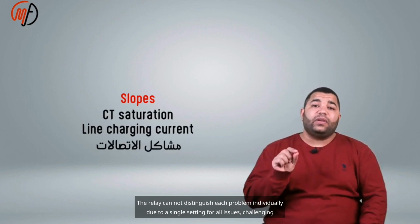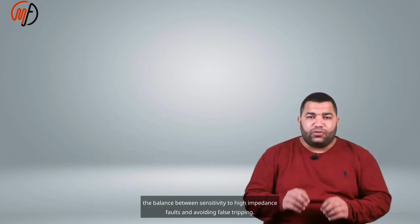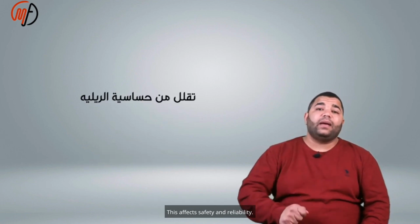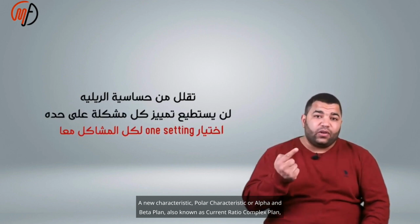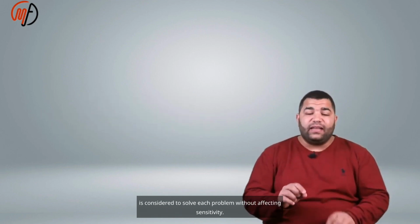The relay cannot distinguish each problem individually due to a single setting for all issues, challenging the balance between sensitivity to high impedance faults and avoiding false tripping. This affects safety and reliability. A new characteristic, the polar characteristic or alpha and beta plane, also known as the current ratio complex plane, is considered to solve each problem without affecting sensitivity.